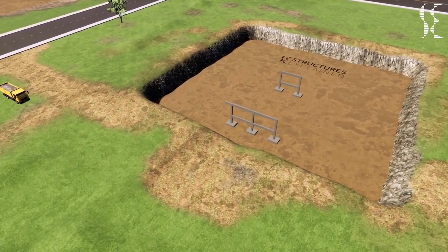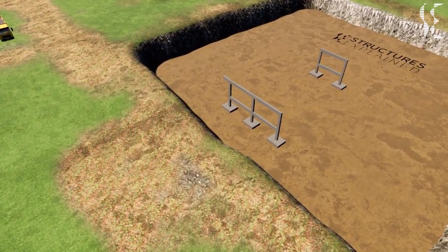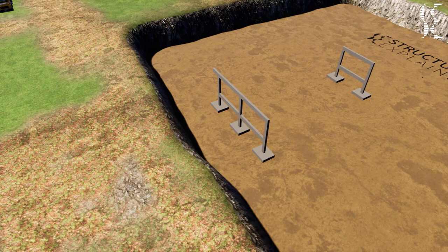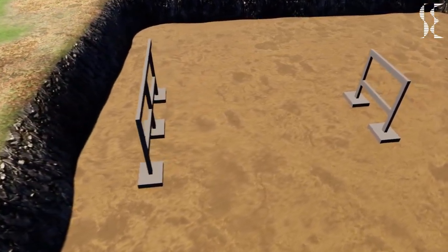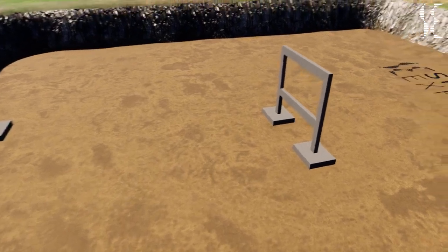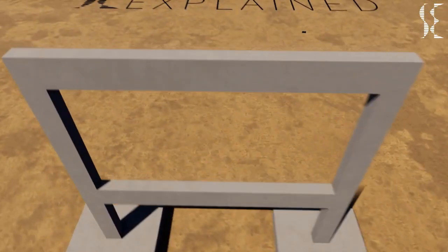Reinforcement is an essential part of a concrete beam. It resists tension forces, increases the compression capacity, enhances ductility, and reduces long-term deflections in the concrete. Additionally, reinforcement prevents cracking of concrete due to shear stresses, shrinkage, and temperature stresses.